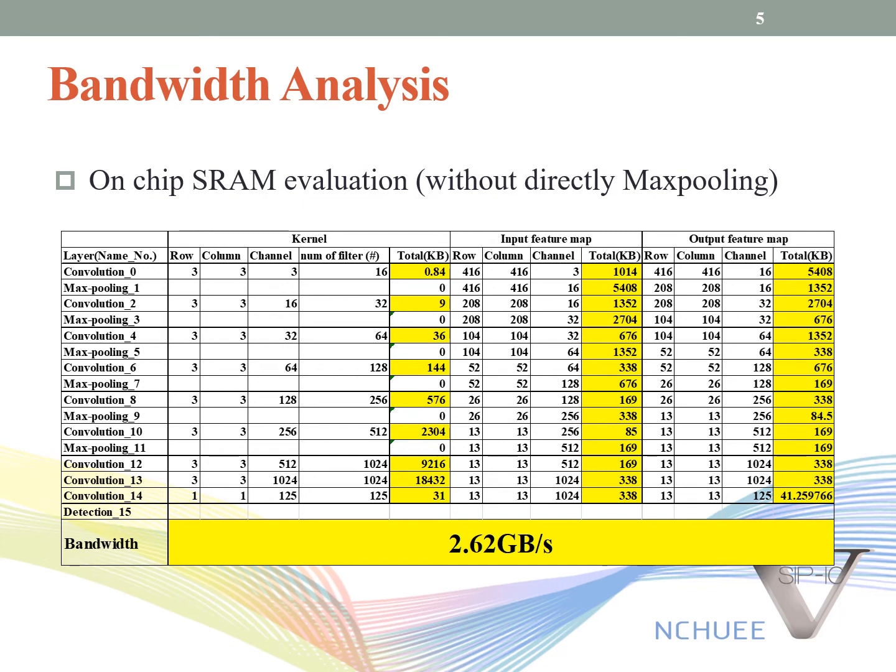Here's the evaluation of tiny YOLO V2 for each layer. The marked values are the total data size of all layers. In the normal way, the output feature will be transmitted to DRAM after each layer is operated. The total bandwidth will be 2.69 gigabytes per second.